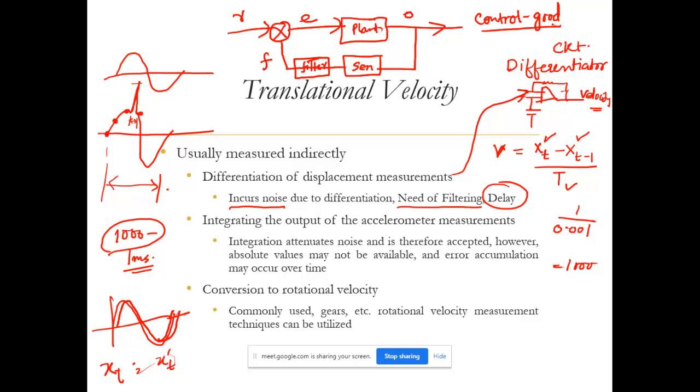for a good control action, which means achieving stability in a good amount of time or less time, which is generally desired, it also needs the sensor to feed the information back to the comparator very quickly. But the moment you start putting filters in between, these filters obviously take some time to process the signal. Filters could be active or passive, where the signal needs to go through an op amp and some resistors and capacitors.